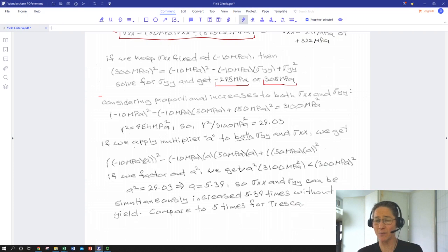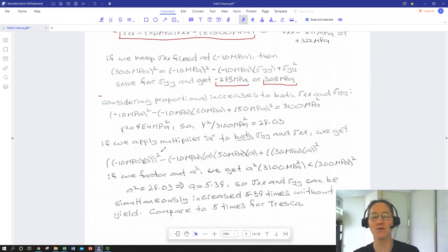What's my max shear in my biaxial loading? How does that relate to my max shear in my uniaxial tension test loading that I got out of my handbook? And the same way with the deviatoric strain energies. So we related test data from a handbook to real data from a real loading scenario through this criteria of either deviatoric strain energy or max shear that brought them together with what makes yield. So that's basically how you use the concept of yield criteria.